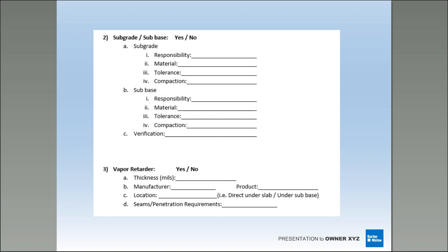Though it may not show in hour 72 after that placement, on day 28 or day 68, or if you're coming in there 4 to 6 months later, a lot of things can happen due to not necessarily the concrete or slab itself, but due to the subbase. You could get some major curling out of it, cracking, a lot of things can happen there. So I would want to know a lot about the subbase, the density, how they're testing it, how uniform it's going to be, and really run through that.